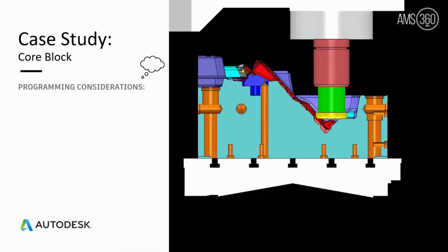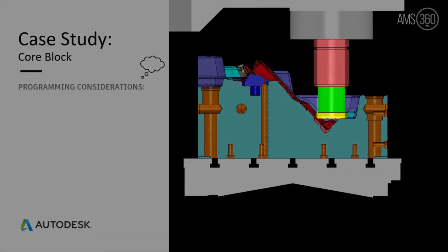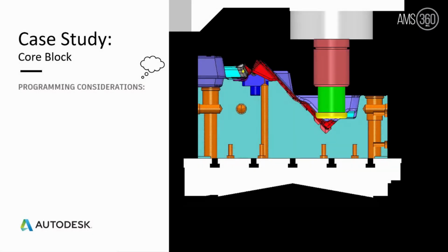Now, experienced programmers will have an ability to look at this job and visualize the workflow. They will pinpoint key considerations, such as using short, rigid tools as much as possible. For manufacturers to adopt automation, we need a solution that will respect this and solve many more deliberations. So, to interrogate the outcome of this automation, let us first highlight 5 fundamental considerations. The first being, can automation show preference for short, rigid tools?